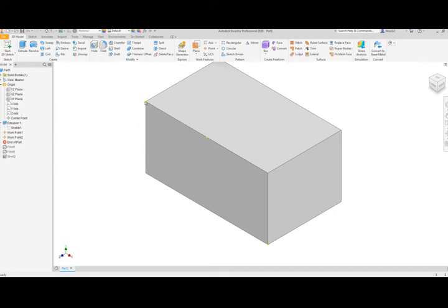The main benefit of points is that it provides an anchor. It also provides the mechanism to create axes. So if I select the work axis, if I select point 1 and I select point 2, it will create a work axis. Same thing here. If I select, say, point 1 again, and then I select point 2, it creates the axis going through those points. Okay. I do not also have to have specific work points to create an axis.